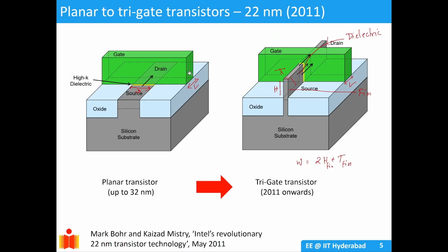Next, we come to planar transistors versus tri-gate transistors. Earlier we were doing planar transistors, where the channel was in the same plane as the source and drain, with dielectric and the gate on top.